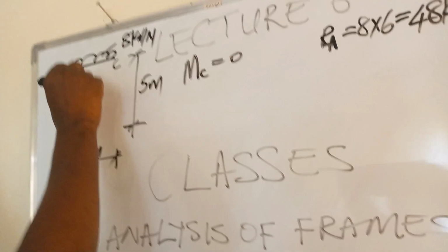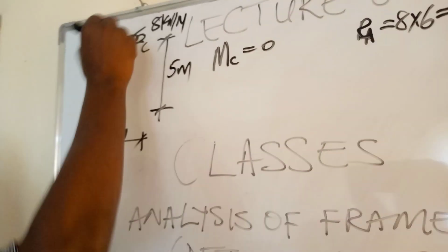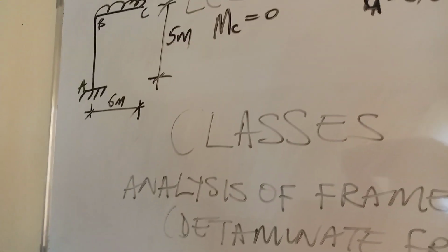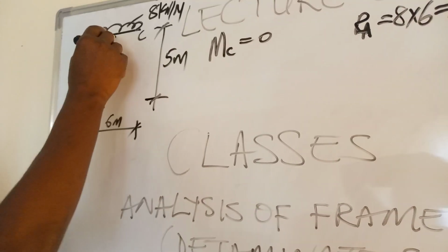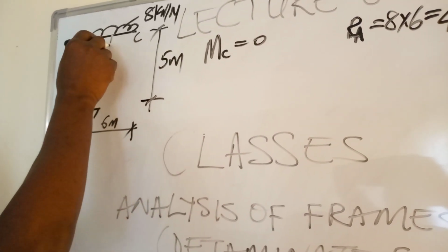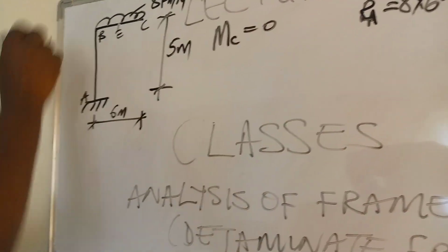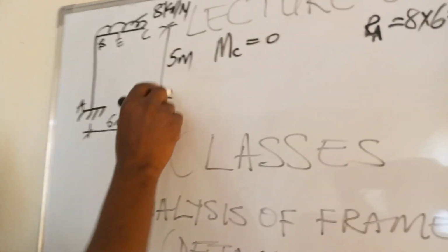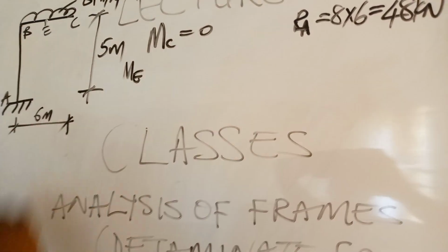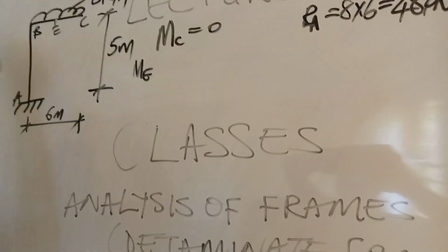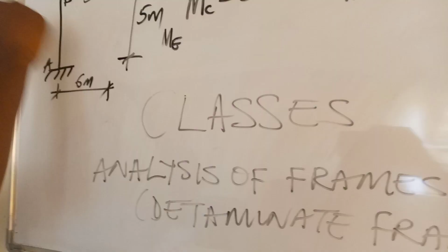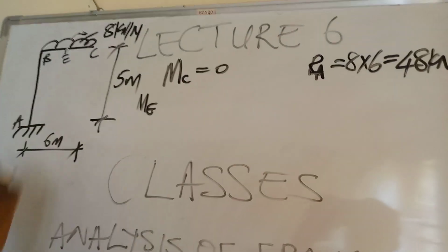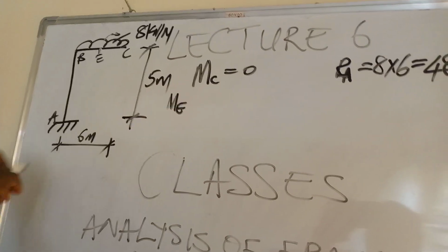After C, we now move. Let's say we want the bending moment at point E, the middle before B. If I want to do it from first principles, I say ME turning towards B, where I started from point C, is positive; any other is negative.